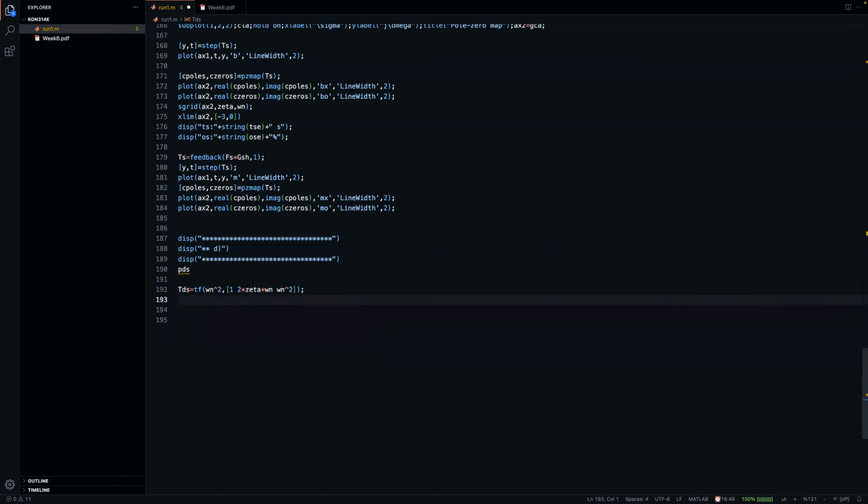So reference tracking. Therefore, our ideal closed loop transfer function should look like this or behave like this. Most of the time, we have additional poles and additional zeros, but we hope that they are far away. For example, one suggestion might be when we have 1, 0, that the 0 should be far away, let's say s plus 20. But of course, then the gain will be modified here. So what we can do is we can just have 1 divided by 20 plus 1. So if you add a 0 like this, this is out of the dominant region, and therefore it would be basically okay to choose here.